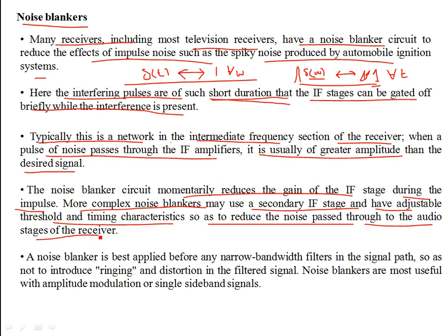We don't need this pulse to corrupt the sound that we are listening to at the audio stage. So these noise blankers are employed in the IF stages of superheterodyne receivers to counter or mitigate the effect of the impulse due to ignition systems and lightning conditions.